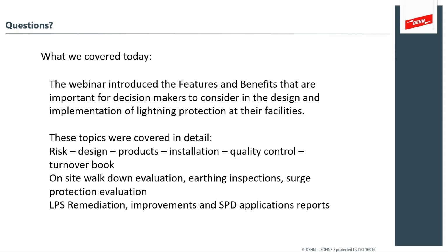Yes. I also just want to add that if you install individual earth rods for a lightning protection system, you need to make sure that you install the adequate number of individual earth rods for that lightning protection system, and also that they are the adequate length in contact with the soil that is in line with the class of lightning protection system that you are implementing and the soil resistivity of the site. I believe if you do those things, you have the correct number of electrodes and they are the adequate length that they need to be, I believe that using earth rods would also provide sufficient protection compared to using a ring.